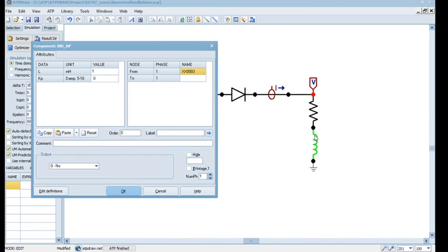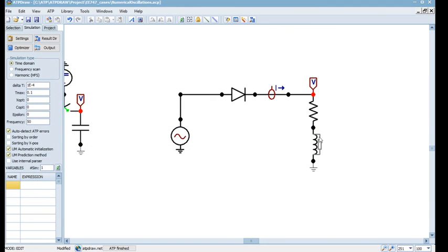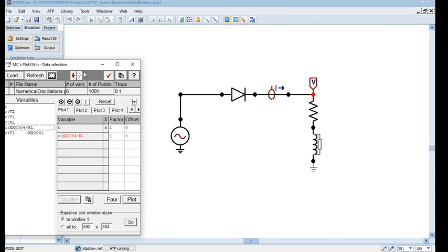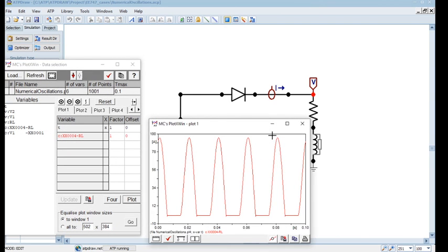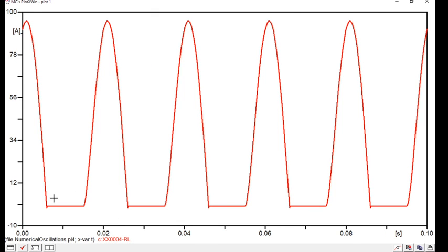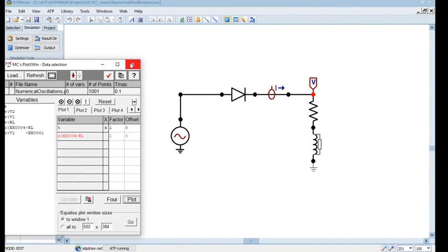What the damping feature does is it adds a resistance in parallel to an inductor. For example, if I specify some damping effect, you will see a small bump coming in parallel to the inductor, so the current won't be interrupted at all. Let me run this again and show you, for the very same step size. So this is numerically handled. You'll get very small bumps, but it's much cleaner in a way.